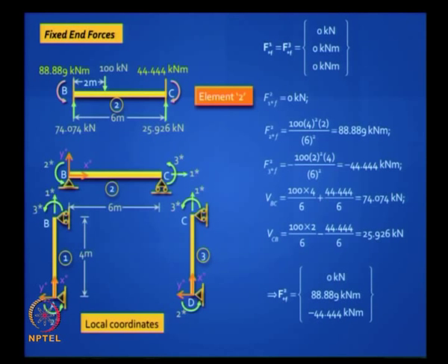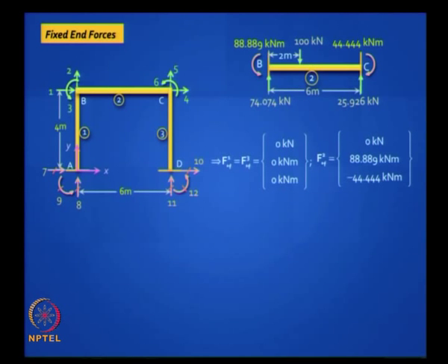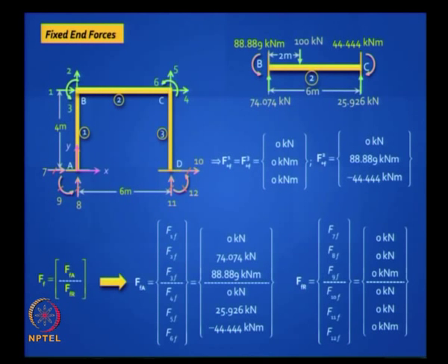Okay, got it? Now what do we do? Now we take this element alone has non-zero fixed end force vectors, and when you want to put it onto that structure, you have to do it by inspection. This is a shortcut method. Reduce element stiffness method, you can't do TD transpose and get it. So doesn't it make sense to write down your fixed end force vector like this, because what are the contributions from the 3 elements? The first and third elements have no contribution, right?